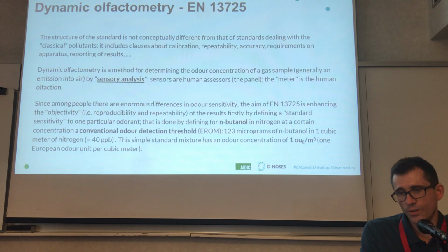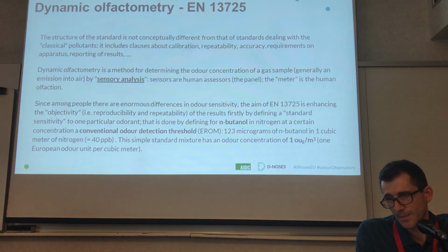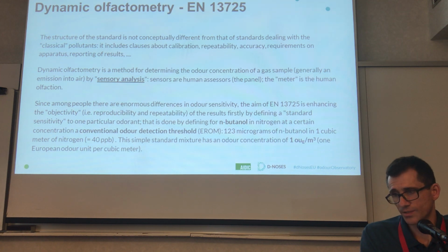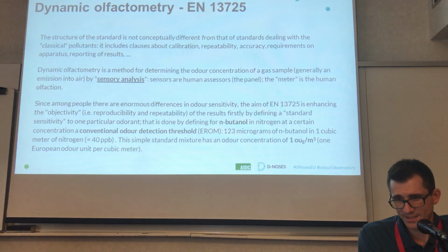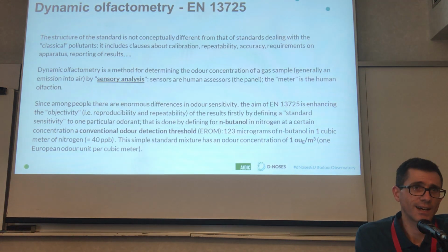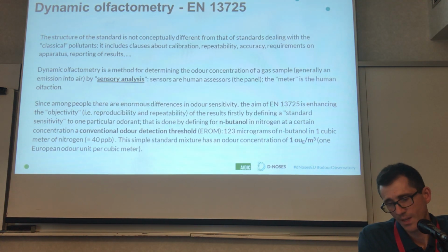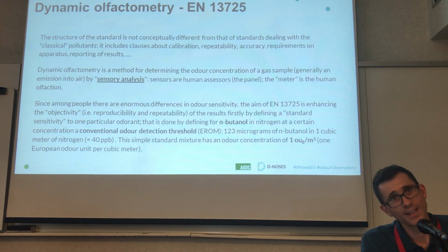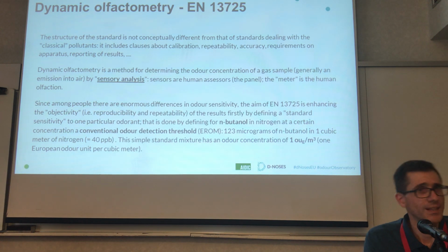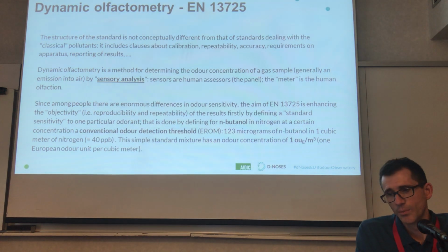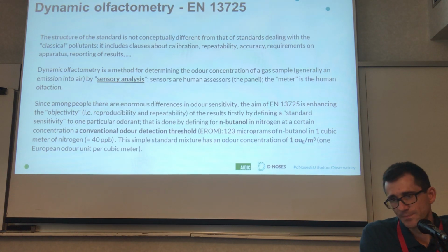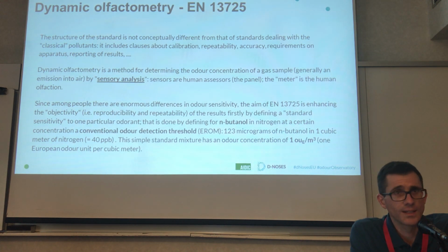The dynamic olfactometry method is a method for determining the odor concentration of a gas sample by sensory analysis. This is the strange aspect of this standard with regard to the other standards of the same technical committee, because it is the only standard that has this peculiarity. In fact, sensors are human assessors.